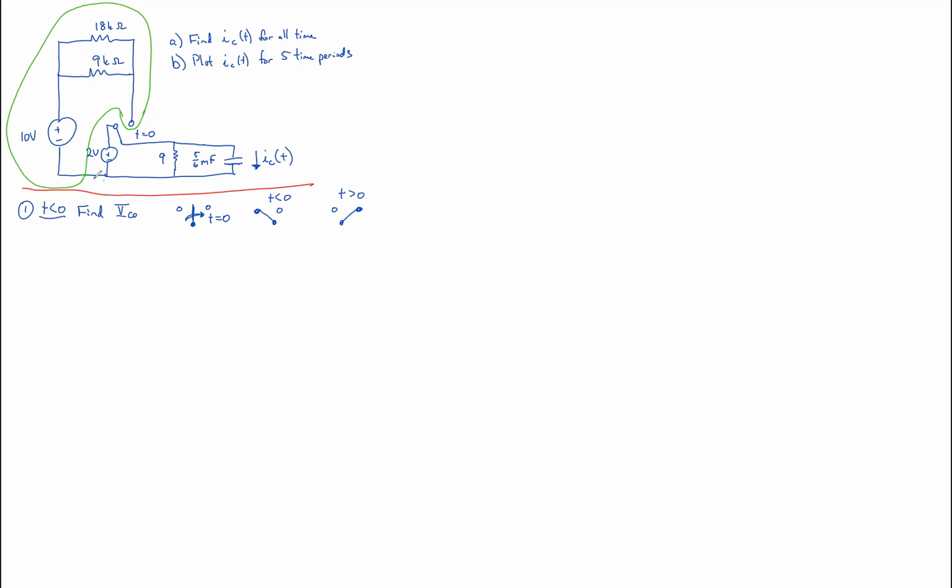And since it carries no current, it doesn't affect the thing we're interested in, which is the voltage across the capacitor. Now, if we were asked to find the voltage someplace here, of course, we couldn't ignore drawing this, because it encloses the part we're asked to find. But in this particular problem, we need to find the voltage across the capacitor. This is outside that part, so we don't need to draw it.